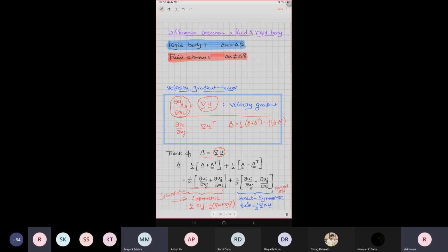Though this angular velocity looks like it is supposed to come out as a tensor of rank 2, it naturally turns out to be a vector. Because of the subtraction, the rest of the components become zero. Only the diagonal elements survive. So basically, when you decompose your second rank tensor into symmetric and anti-symmetric parts, the symmetric part is still a second rank tensor called the strain rate tensor, but the anti-symmetric or skew symmetric part converts in some sense to angular velocity, with the non-diagonal elements becoming zero. This has a very important property when we learn about vortex flows.